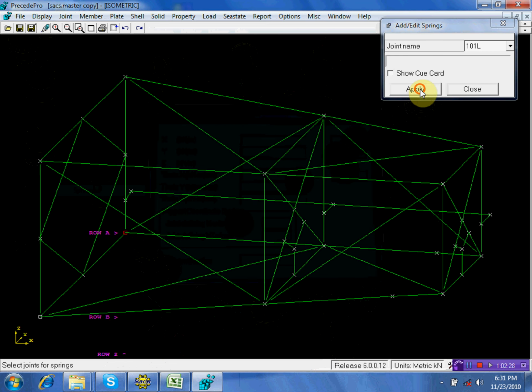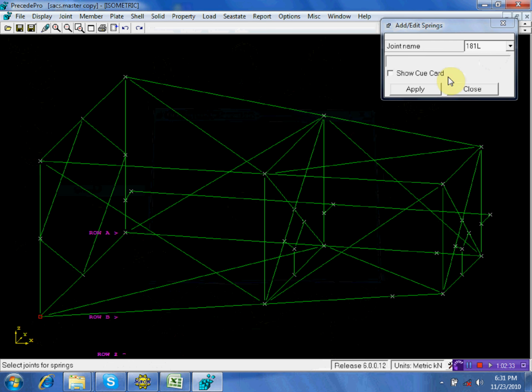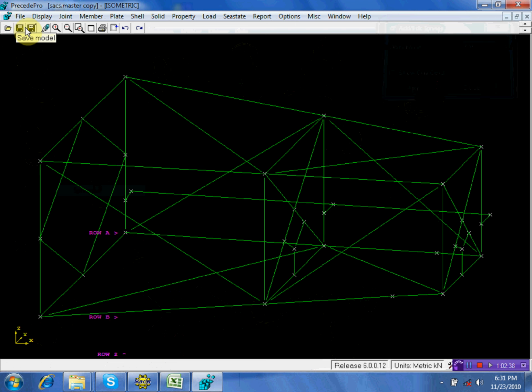Okay, we haven't got the basis of design for jacket loadout. So what will you do as a structural engineer? For example, I will not give you that the deflection is 25 or 50 or 30 or 60, different from the top side. So what will you do? In the absence of specific data, because some clients will specify we need only 25 mm or 50 mm.